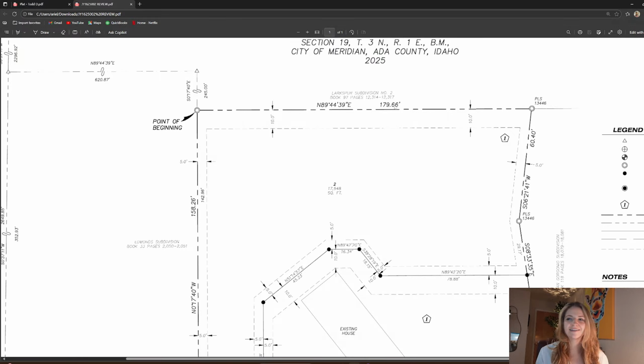It's late, I'm tired. But that's basically saying it's 179 feet, 8 inches long, but it just does it in a decimal instead. So you're going to specifically type in 179.66 feet for that length.